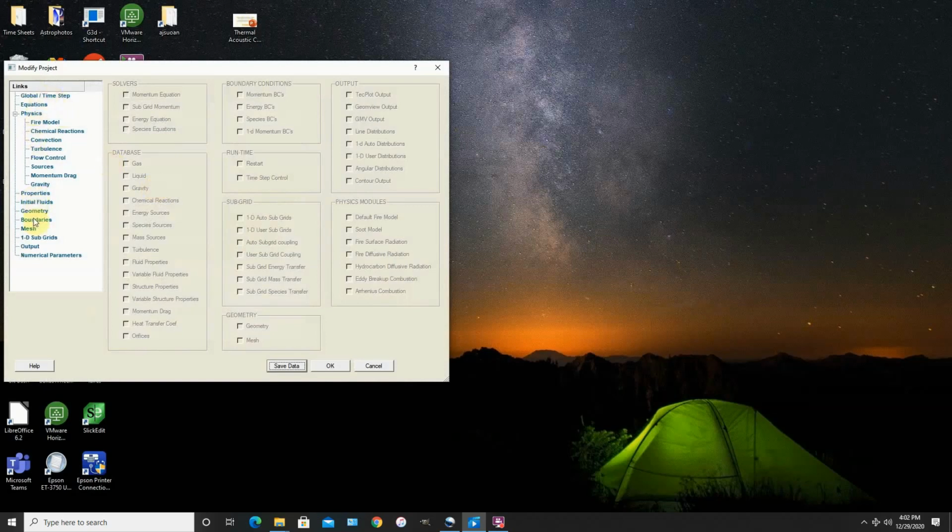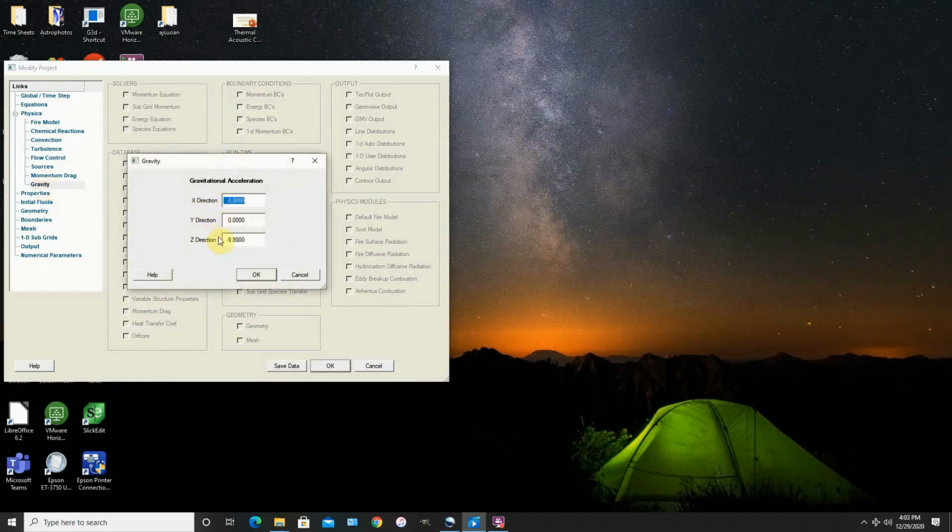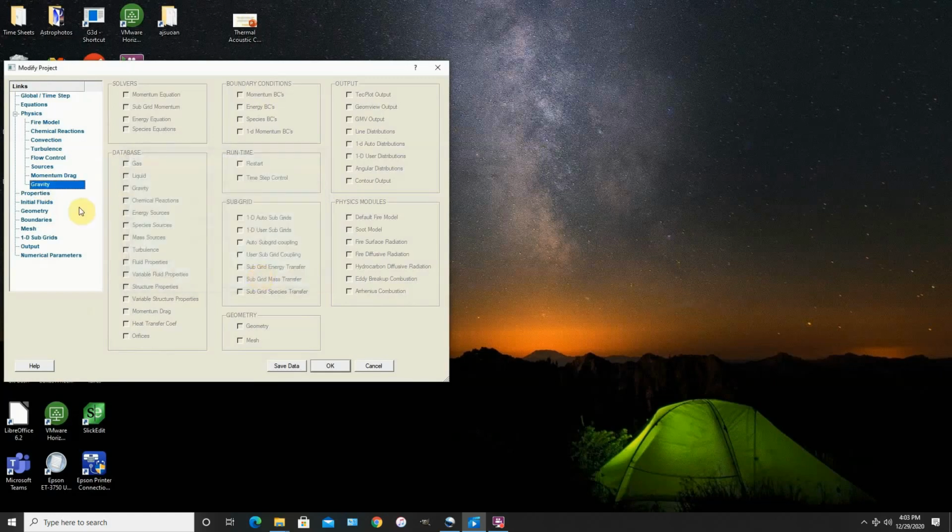These are set up in the way that you would want to enter the data. The time is initially set up to run one time step so that you can see if the problem runs and to get some data without actually going too far. The equations are set up for combustion at the moment, so we don't need to do anything with those parameters. One thing I should mention, the z coordinate is up. All right, so the acceleration of gravity is minus 9.8. Everything is in SI units, so I'll be presenting things in kilograms, meters, seconds, and so on.